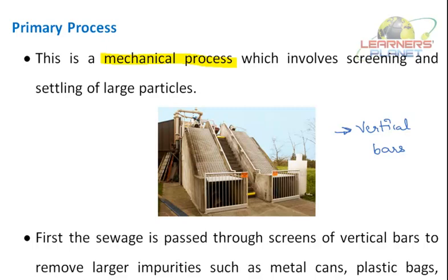So this level is sometimes referred to as mechanical treatment, although chemicals are often used to accelerate the sedimentation process. Sedimentation, do you remember, students? Sedimentation is the process where the solid or heavy particles settle down at the bottom of the container or the beaker, right? So primary treatment can reduce the oxygen depletion level of the incoming wastewater by 20 to 30% and the total suspended solids by some 50 to 60%.